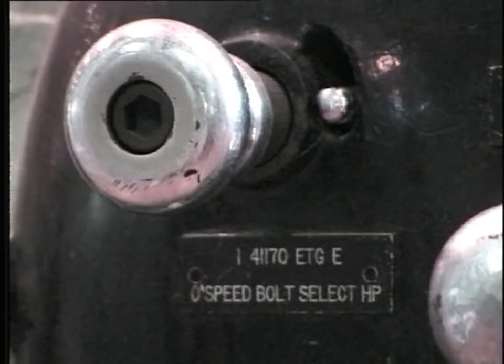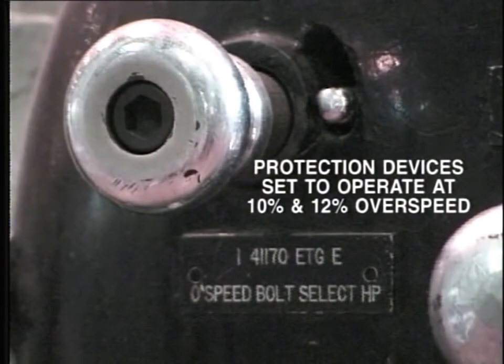In order to prevent this possibility, 1 and sometimes 2 quite separate overspeed protection devices are installed and set to operate at 10% and 12% overspeed. Each protection device operates a trip relay to close the stop valve and other protective action as already discussed.